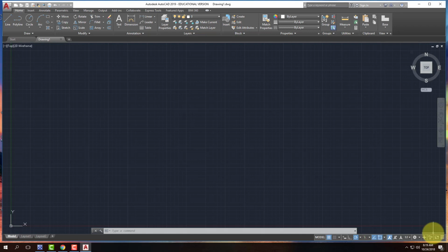I think one of the important things about AutoCAD, or several of these major design software, is that we actually draw things in full scale. If I were designing a building and that building was 20 feet long, I would draw it 20 feet long. So everything is at full scale. We deal with scaling down when we go to print. When we do layouts, when we do viewports, that's when we do scaling. When we're in model space here, everything that we draw is full size. So it's easy. There's no math in your head. You just draw.